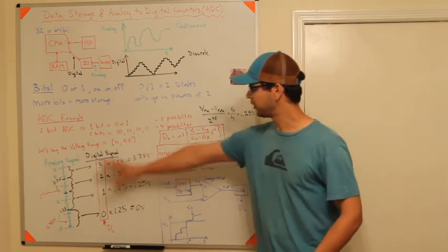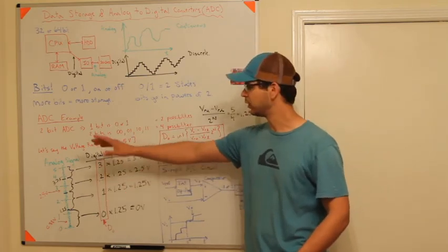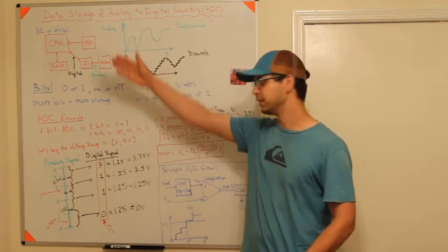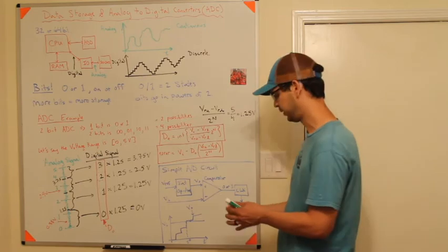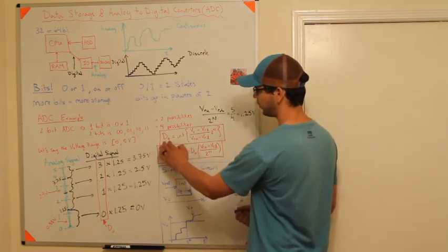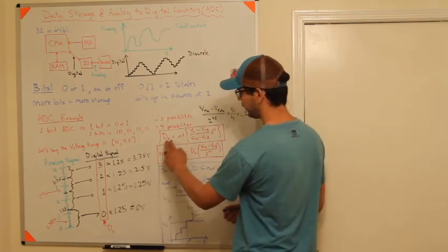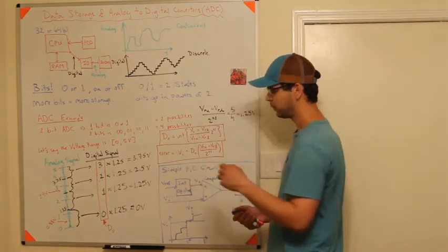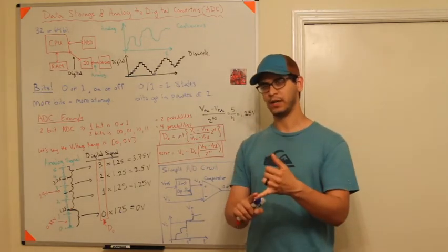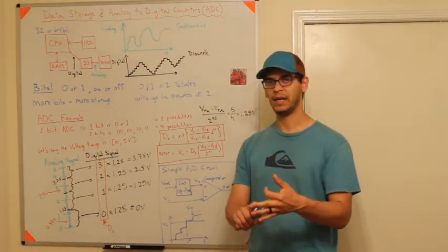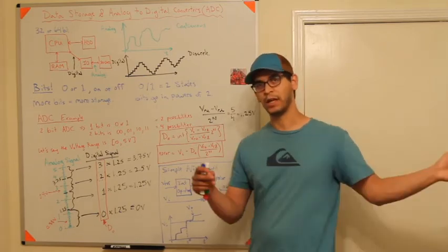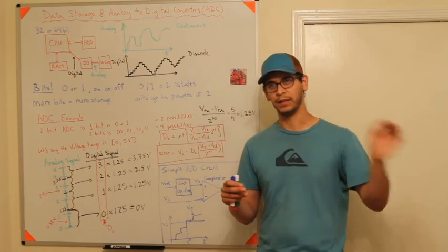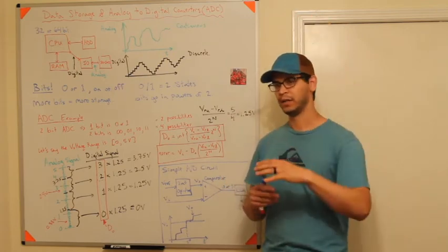Now, all of this is pretty difficult to do for higher order ADCs, so there are some simple equations in your textbook that highlight all this. If you want to compute the digital output, you use the integer function. Depending on whether you're using a calculator or Python or MATLAB, the integer function will either round down, truncate, which means it'll just remove the decimal point, or round up.